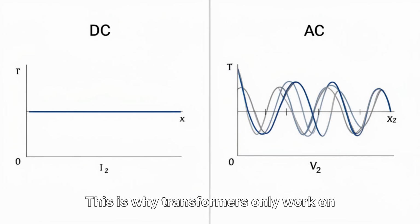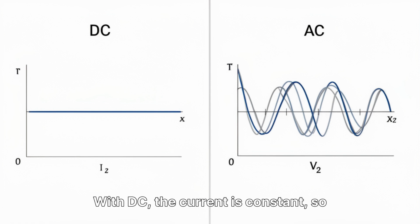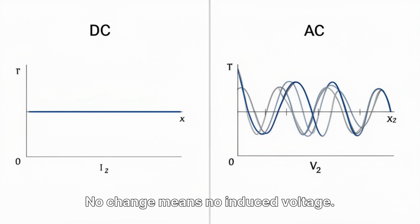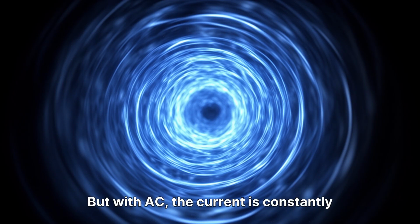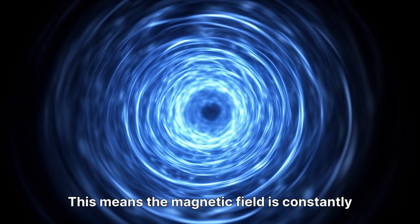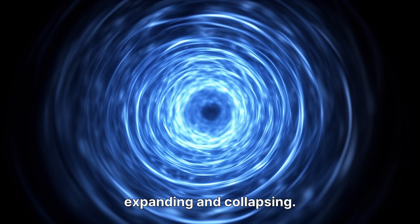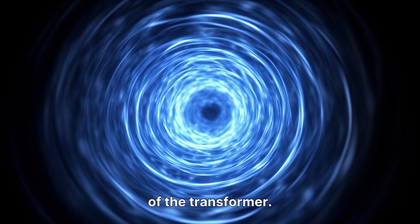This is why transformers only work on alternating current, AC, not direct current, DC. With DC, the current is constant, so the magnetic field is constant. No change means no induced voltage. But with AC, the current is constantly reversing direction, 50 or 60 times a second. This means the magnetic field is constantly expanding and collapsing. This dynamic magnetic field is the heartbeat of the transformer.